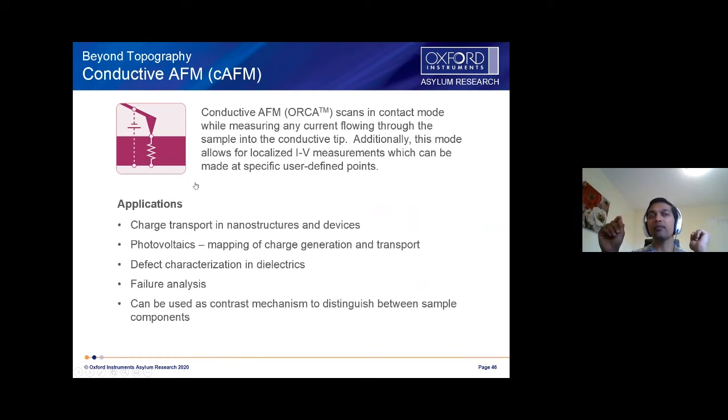In conductive AFM, we are feeding back as in a regular AFM technique. You are scanning the surface line by line and the feedback is like standard AFM feedback, but separately, on the side, you are measuring the conductivity variation in the surface as an additional channel. So you are not relying upon the electrical signal as your feedback parameter. Your tracking on the surface is in standard AFM mode, but you are simultaneously measuring current. In STM, you are getting the surface topography using the current data.